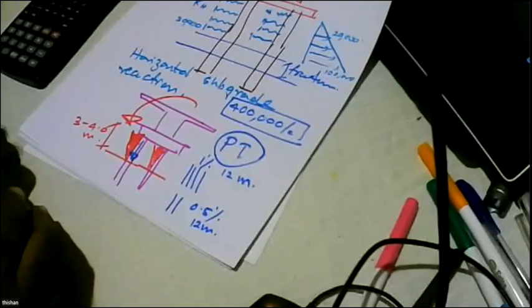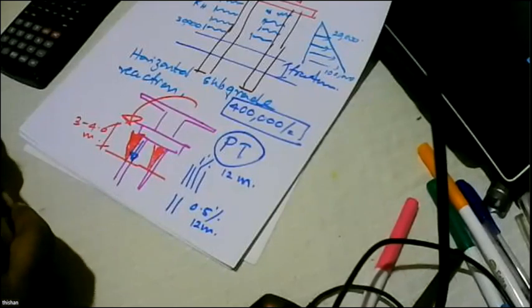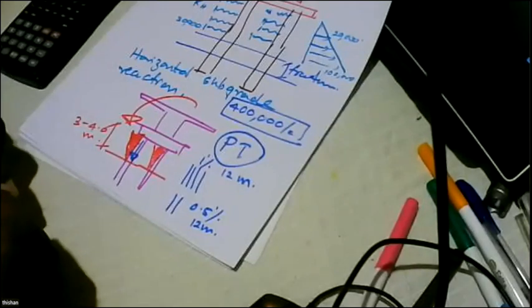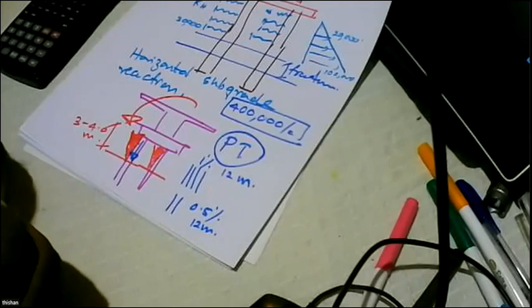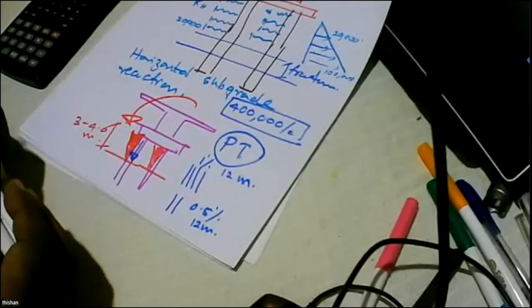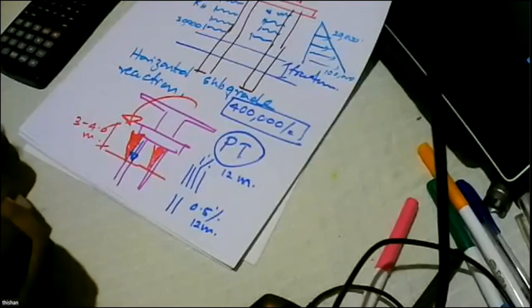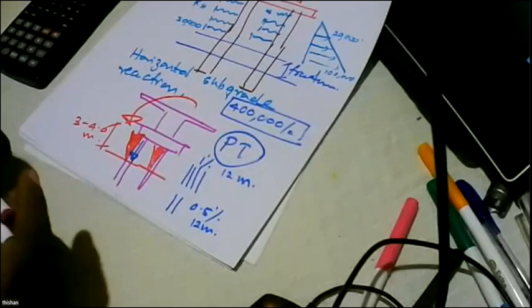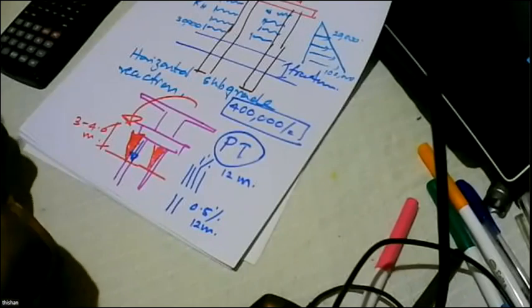But in the case of bridges, I don't mind having some reinforcement, because the scour damage might expose the piles unnecessarily, and that might endanger the pile. So it might be a good idea to have some nominal reinforcement, considering that the pile is a lightly loaded reinforced concrete structure. And for lightly loaded reinforced concrete structures, the Eurocode specifies 0.2%, but Eurocode also specifies a minimum reinforcement of 0.5% for piles if you are providing reinforcement.